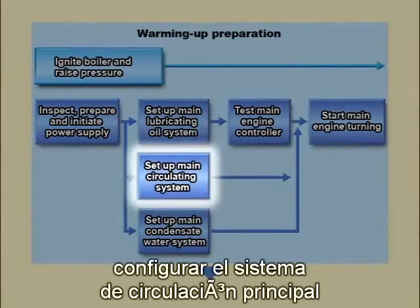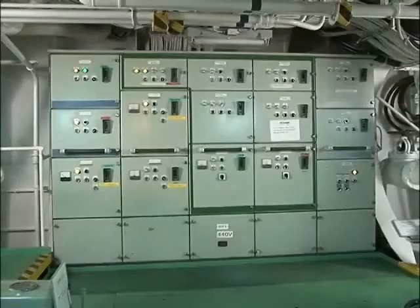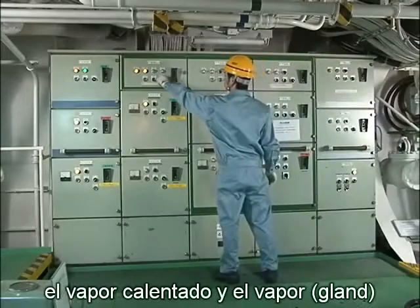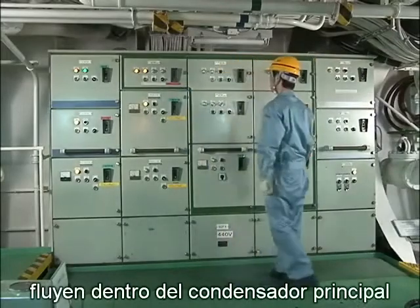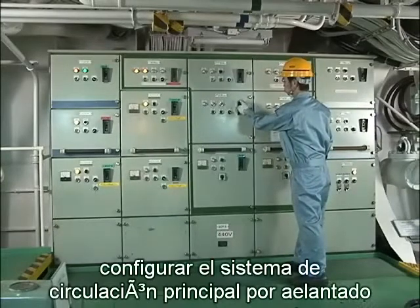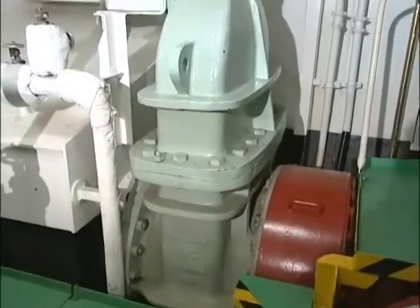Set up main circulating system. As warming up begins, warming up steam and gland steam flow into the main condenser. To prepare for cooling such steam, set up the main circulating system in advance by starting the main circulating pump.